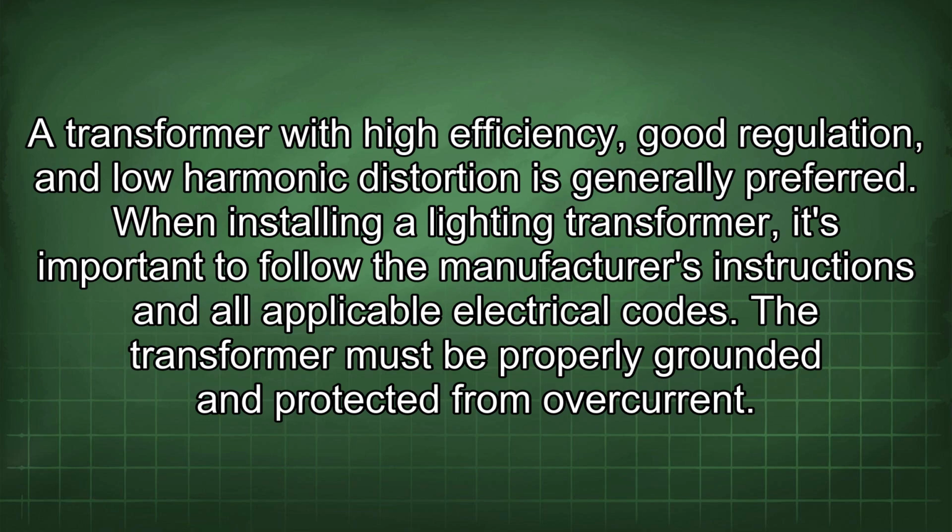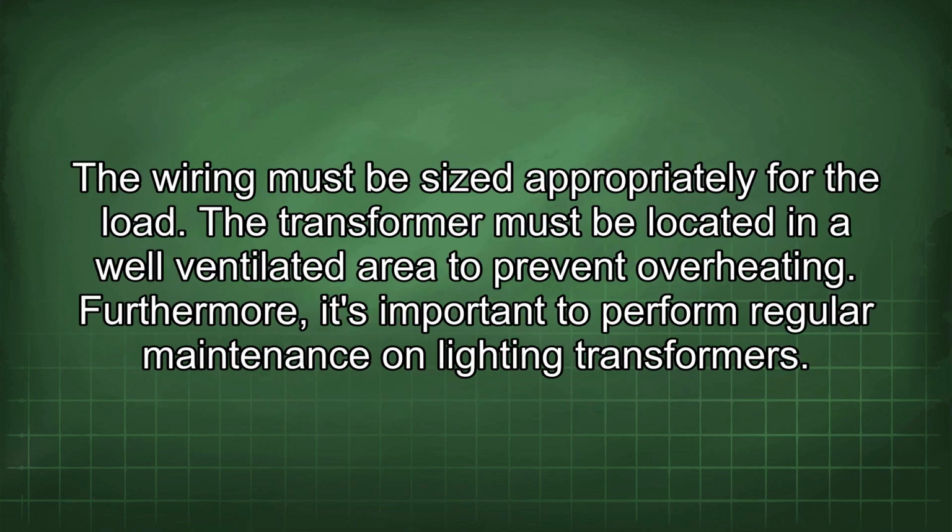When installing a lighting transformer, it's important to follow the manufacturer's instructions and all applicable electrical codes. The transformer must be properly grounded and protected from overcurrent. The wiring must be sized appropriately for the load. The transformer must be located in a well-ventilated area to prevent overheating.